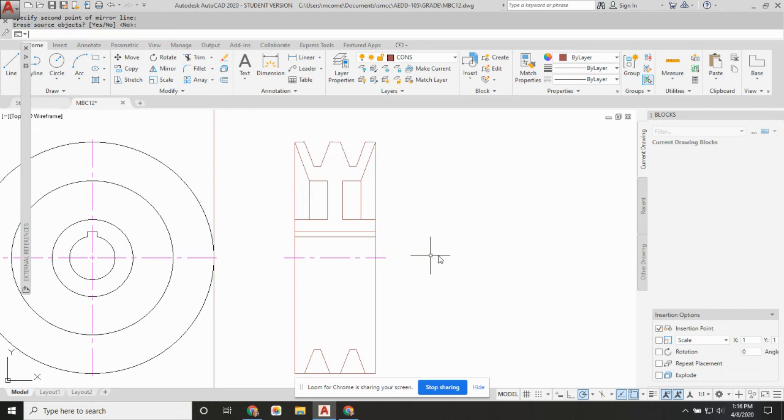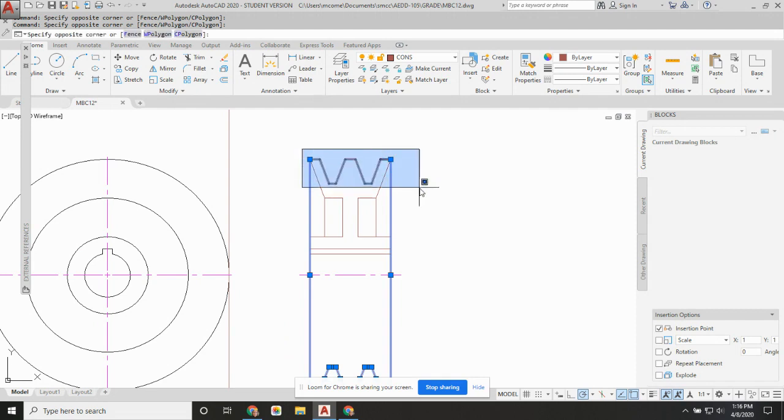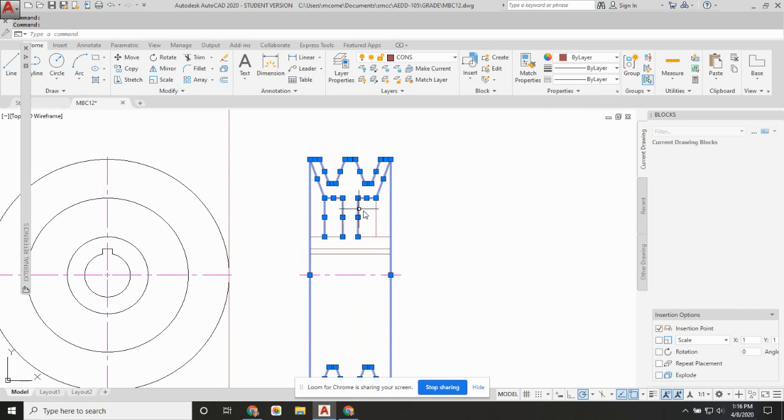From the center line. And if I trim between those two, that's what we'd see down below. So using the object layer, let's go ahead and make these lines and these lines and these lines, also these lines here that are defining the edge of the object. Those are all going to be object lines.